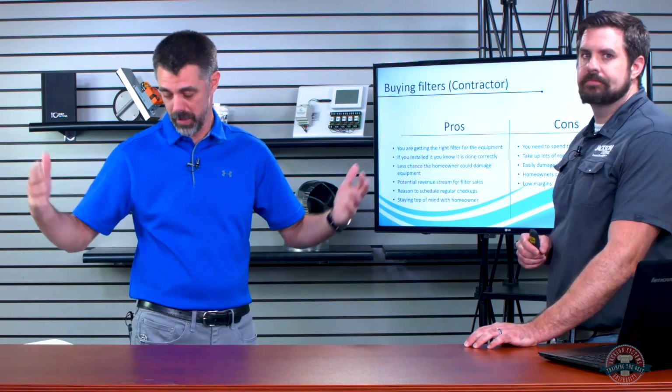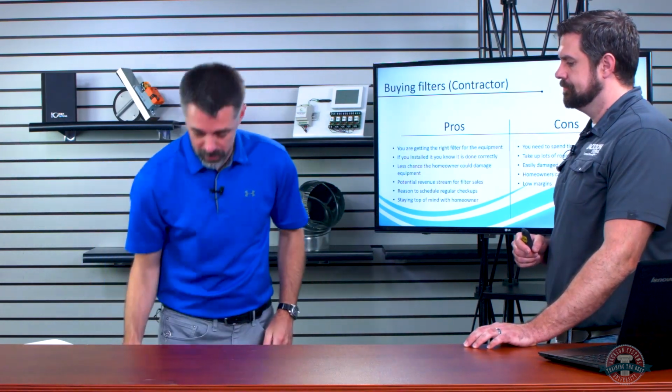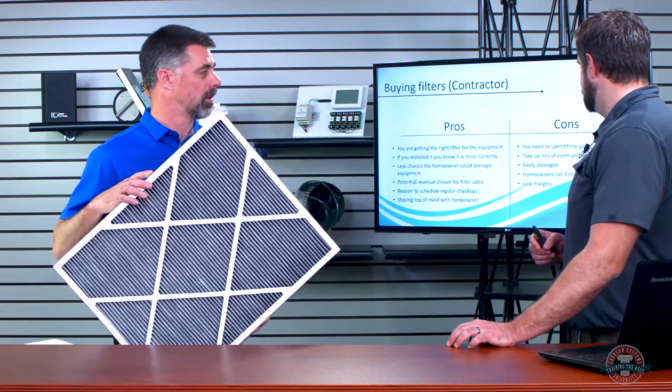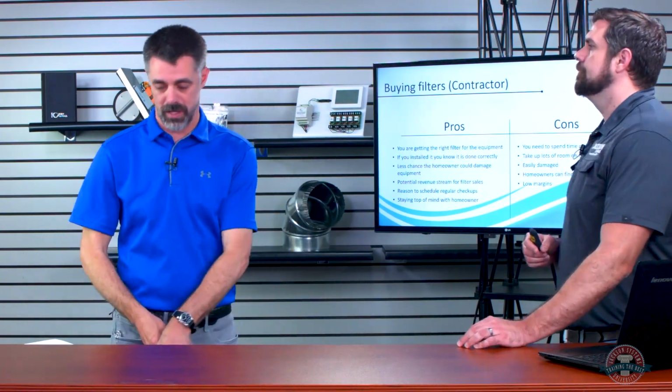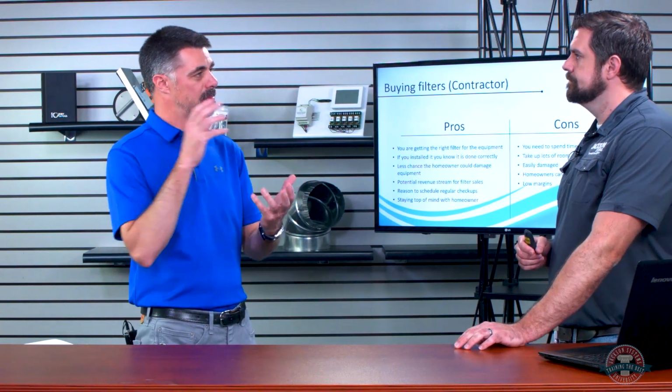When I was in a service truck, I actually made, I can't tell you how many different, three different service trucks, I made a large filter shelf just to be able to put these big filters onto the truck and not damage them. Because the worst thing I had with filters on the truck was I pull them off, they're smashed, whatever, right? Then I go to slide them into that rack and I'm bypassing air, and then I'm defeating the purpose of having a filter in there. Right. Now I'm just getting the equipment dirty by letting all that air go around the filter. So there's a lot of trade-offs on there.